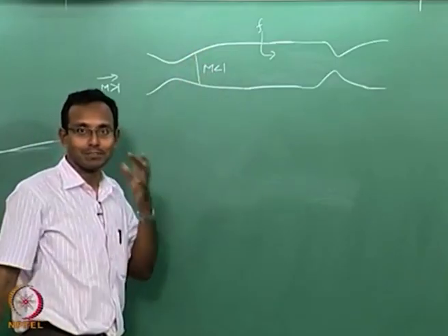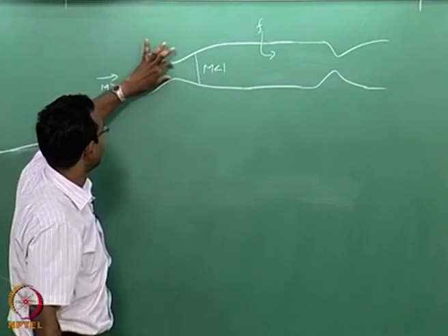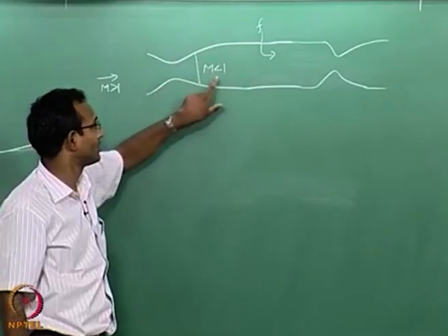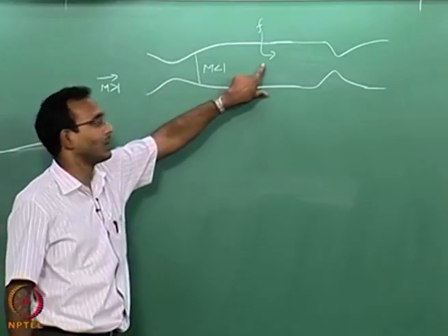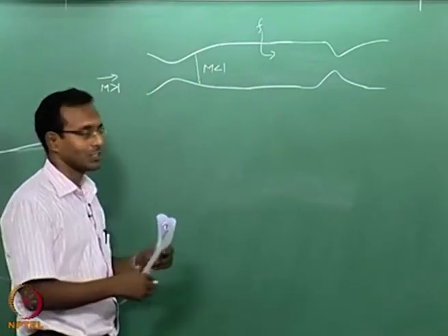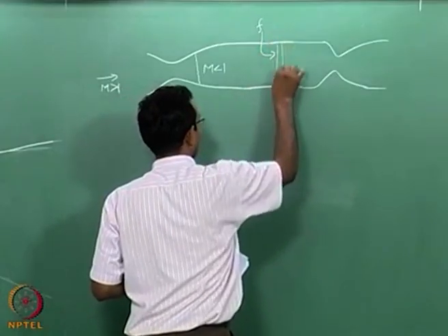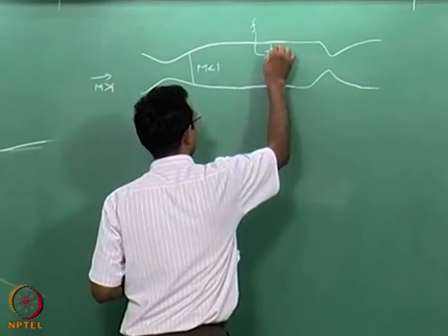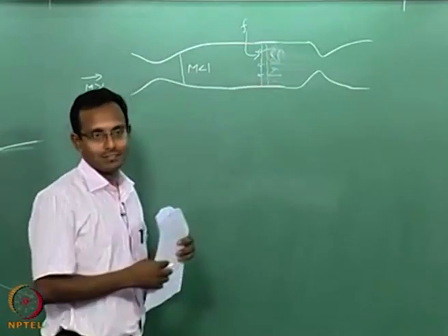This is what really happens. Shock is sitting here, M is greater than 1, it jumps across to this condition, and then from here I added fuel, and I am having subsonic condition. Of course, now I have to think about a similar thing, I need some flame holder and injector, etc. There is going to be fuel added to the system and there is supposed to be a flame holder and there will be burning in here, something like that.